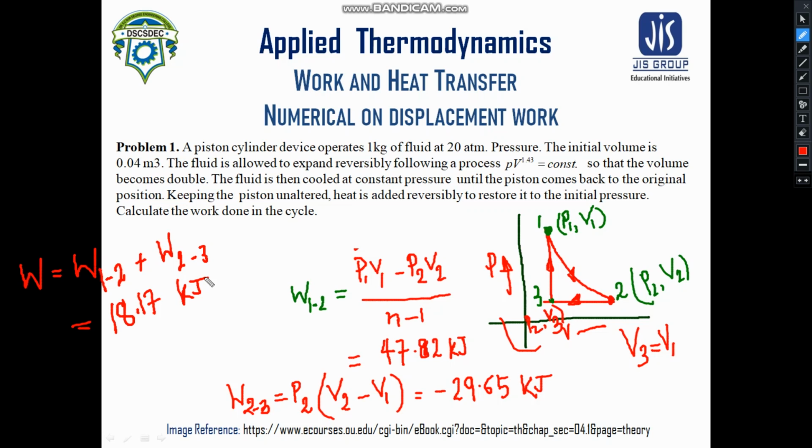You just need to understand the nature of the thermodynamic process, and you will find a certain thermodynamic relationship is always given for this process. A pressure volume relationship is given to you, and whenever you know that pressure volume relationship, you can put it into the PdV equation, and then you can get the desired data.